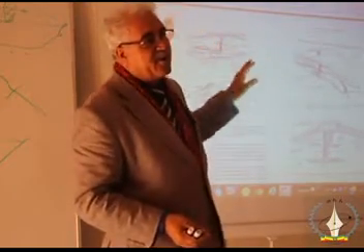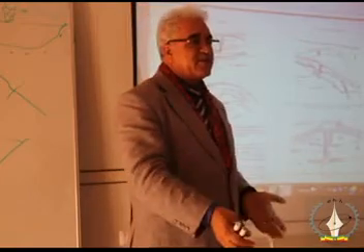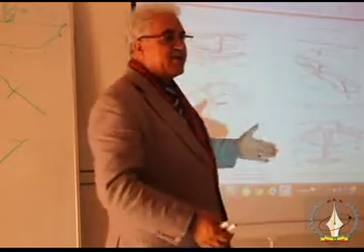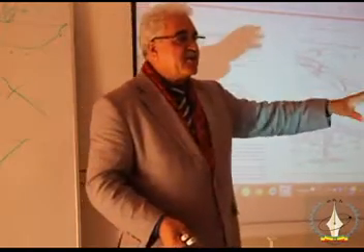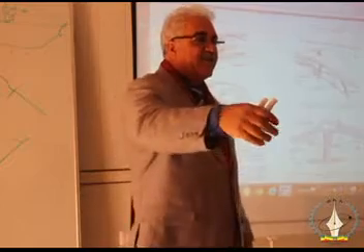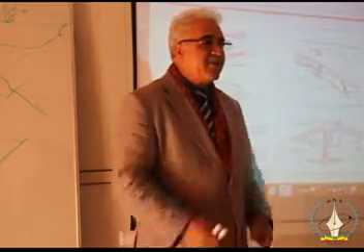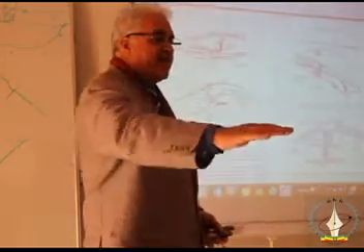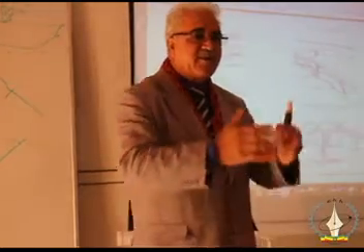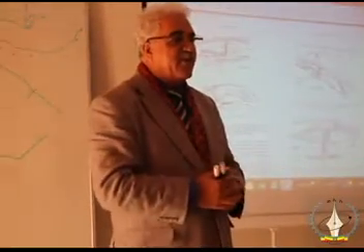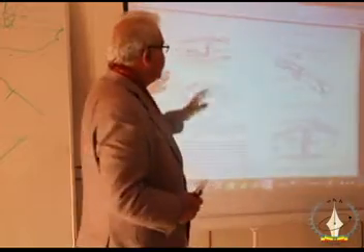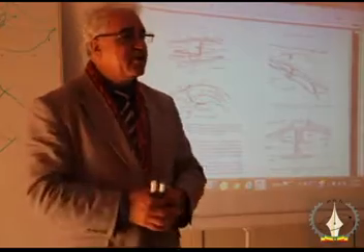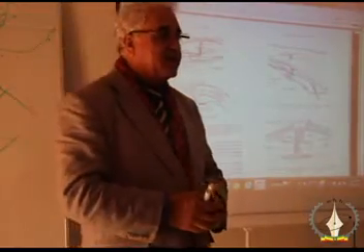And when the ship comes from upstream, they just do the reverse, which means that once the ship is in, they close the upstream gate, they close the valve, and they open another valve for the water to go downstream. So then in the basin, the level goes down, down, down. When it is the same level as the downstream water level, they open the gate so the ship can go downstream. So if this is such a river, then you have to include a navigation lock.